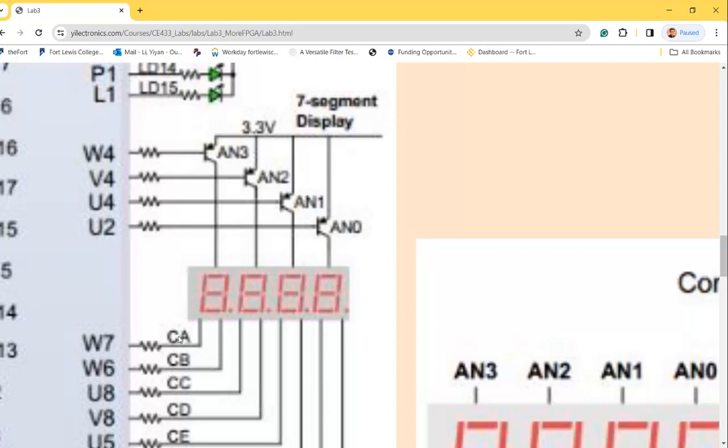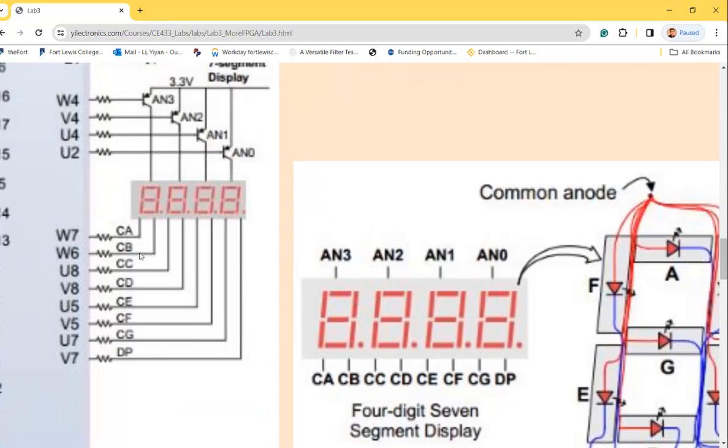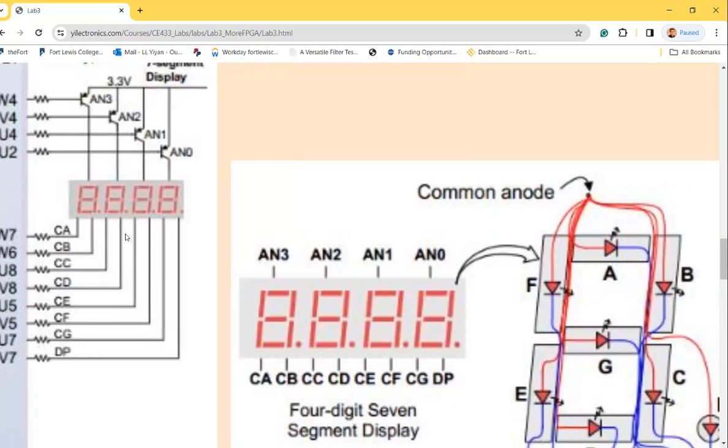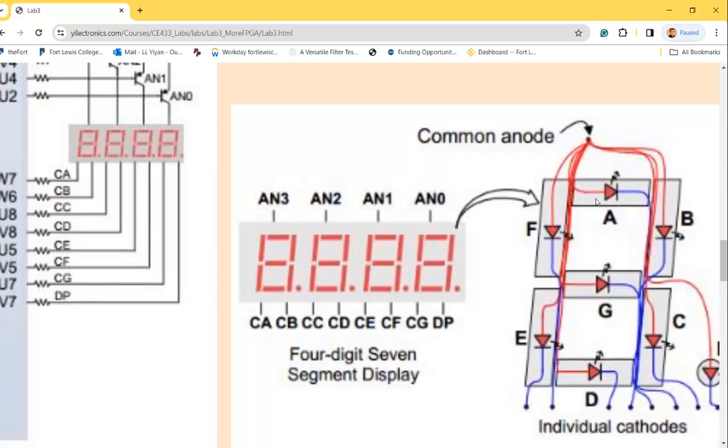So, you see A here, CA, CB until CG, CP. These indicate that it's turning on, off, controlling one of the LEDs in one of them. It's a little bit confusing because I have 4 units. Actually, all the 4 units are being shorted together. So all the A's are being shorted together, and all the B's are being shorted. It's trying to multiplex all the digital pins.